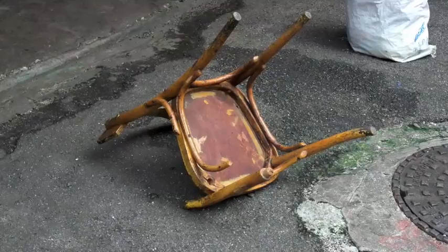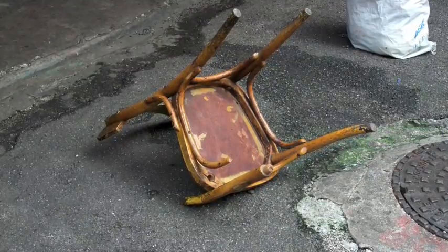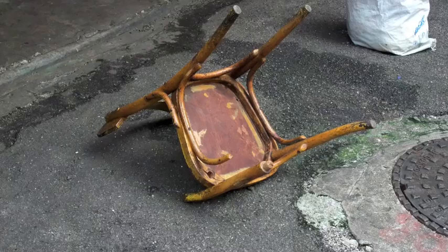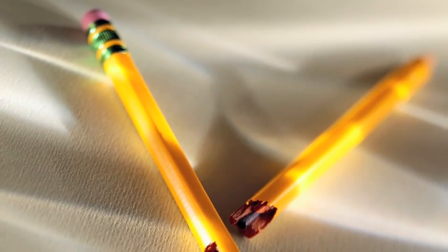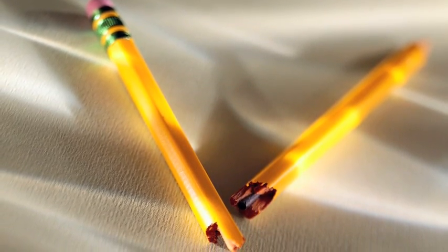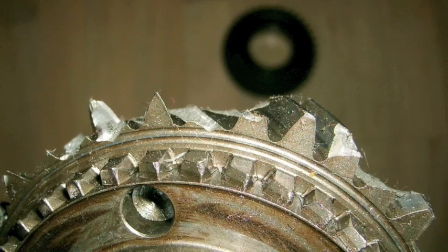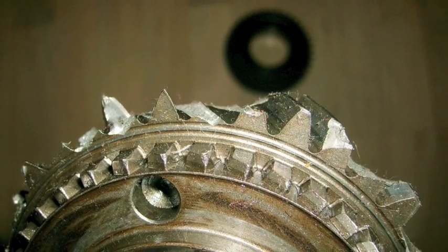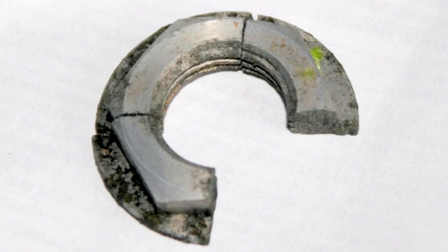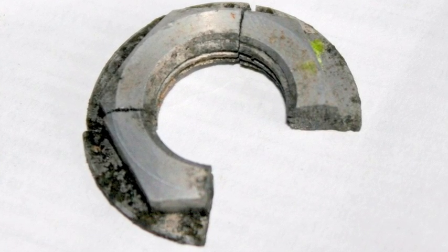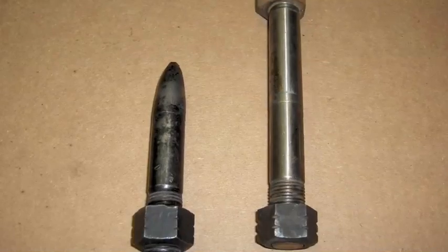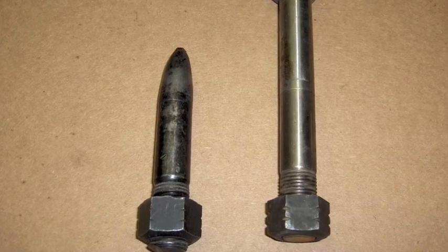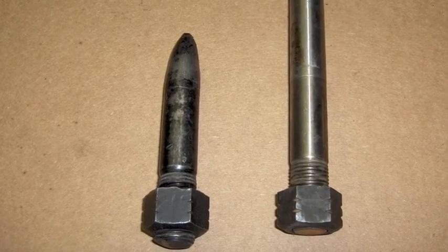Because these structures are not only a matter of convenience, but also important to people's safety, the structures are designed to have an allowable stress that is less than the material's ultimate stress by a factor of safety. As engineers, we try to design a structure so that the maximum stress the structure experiences does not exceed the allowable stress. This makes sure that the structure does not fail during its intended use. This is why it is crucial to study stress concentration as well as distribution of stress within a structure.